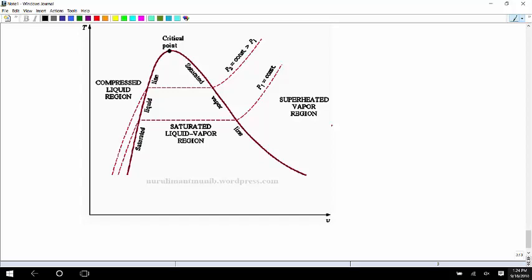But now you're getting a huge, little by little, a huge change in the specific volume as the temperature stays the same. Until finally it's all steam. You don't have any liquid water left. And at that point, if you keep heating it up, all of the vapor becomes superheated, and now it would take taking energy away in order to get it back into like a visible steam where it can condense again.